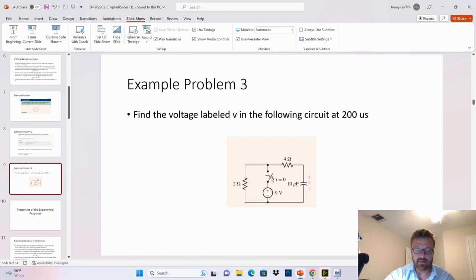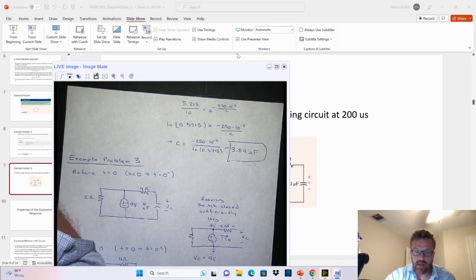Basically, what had happened was, we're assuming this voltage source was driving this circuit up until our reference point of time, which we're calling 0. And at that point in time, we open the switch up. All that's going to happen is whatever energy is stored on this capacitor is going to be dissipated in the resistors in the actual source-free response. So let's look at how we would do that.